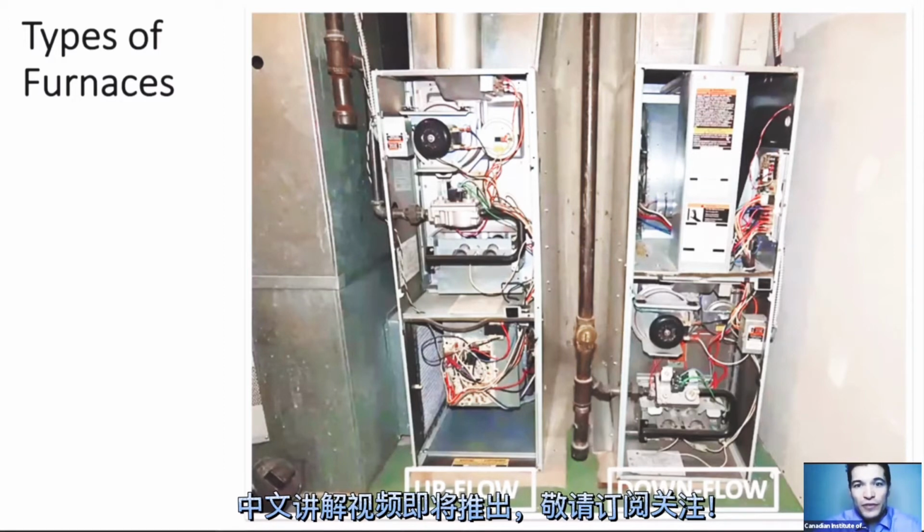After you check the furnace filter, you might want to take a look inside the actual plenum as well, because in the image on the left you have the filter rack, you can pull it out and look inside the plenum. After you take a quick look down there, take a look inside the furnace cabinet. You can start with the lower one or the upper, it really doesn't matter. Again, you want to be checking for any sort of debris or corrosion. If there's a motherboard, with more modern furnaces, check for any loose connections or scorching, because that may impede the way the furnace functions. Look for any flame rollout, which we'll talk about in a little bit, corrosion, and watermarks. And of course, your audio and visual clues as well.